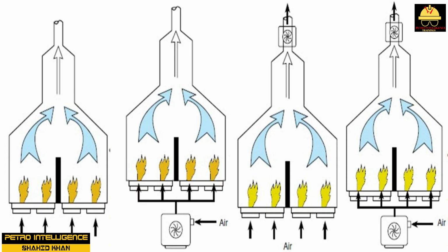In a natural draft furnace, buoyancy forces induce draft as the hot air rises through the stack and creates a negative pressure inside the firebox. This pressure is lower than normal atmospheric pressure. Forced draft furnaces use a fan to push fresh air to burners for combustion. Forced draft is used in furnaces that preheat the combustion air to reduce fuel requirements.